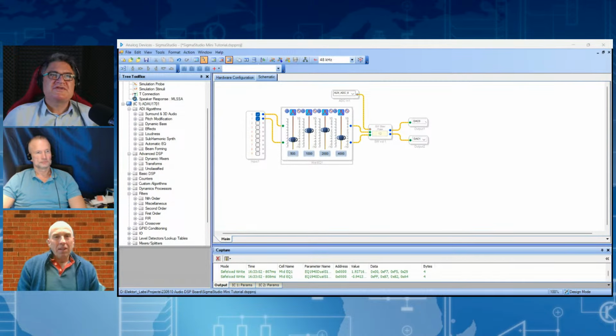Yeah, well, we do ask selfish questions, Clemens. I know Jens is all about latency because he's working on projects where latency is very important to him. And of course, I ask about voltages and opto-isolators because of what I'm working on. Last time I connected an Arduino directly to a keyboard MIDI, that was fine because they were both 5 volt TTL. But as you mentioned, and I'll reiterate for the audience, MIDI has built in an assumption that all inputs will be opto-isolated, correct? Well, if you adhere to the MIDI standard, then yes, that is the whole point.